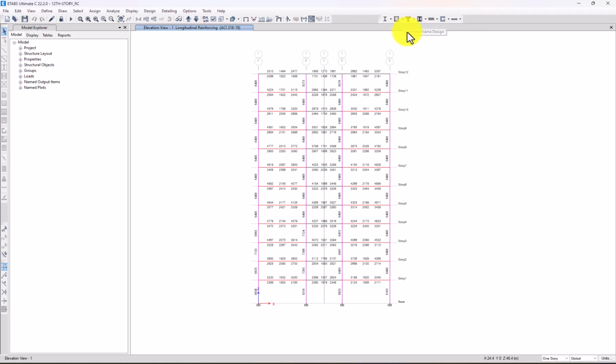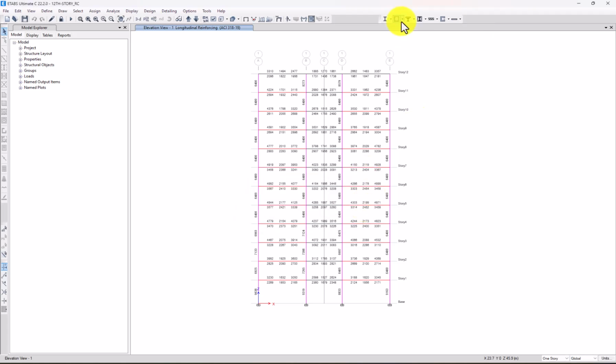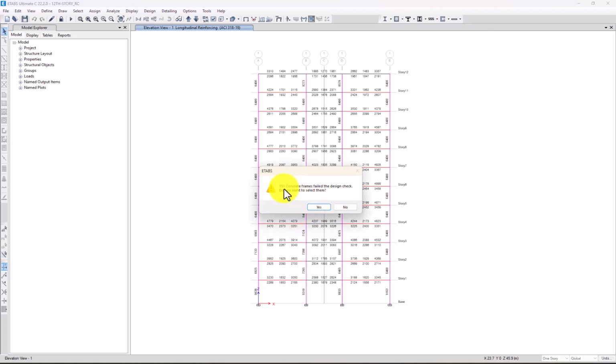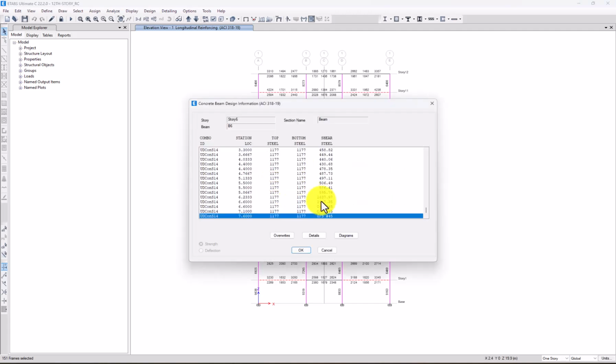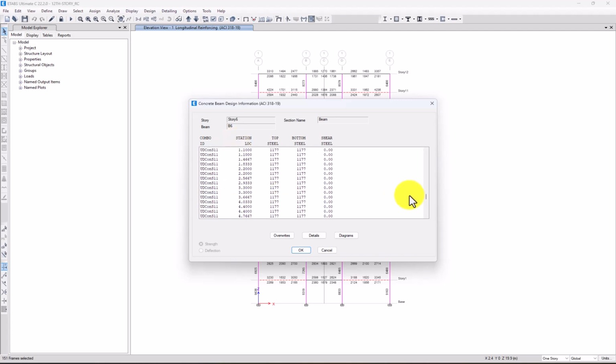And additionally, we also can verify this one. We can verify the design, and all sections are passed, and also verify all members are passed. Here is something called 150 concrete fail to design check. Yes, because some of the ones we selected are beams in some combination, which is in the slab. So remember, this is called slab design. So it doesn't pass, and we don't consider that the slab should be passed, because that's for the slab design. But mostly we have the first two five for the concrete, which is passed.